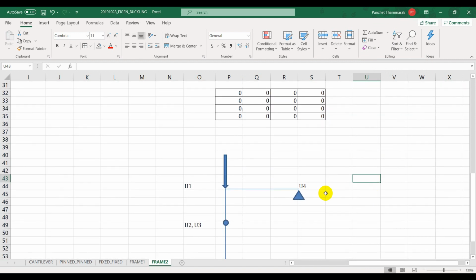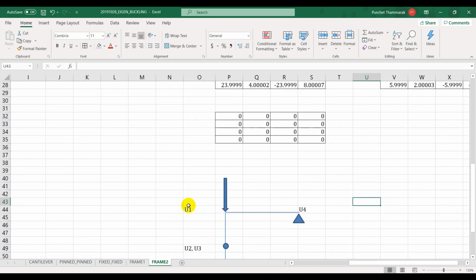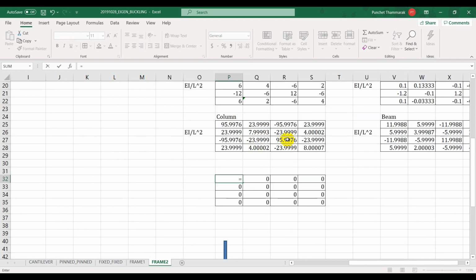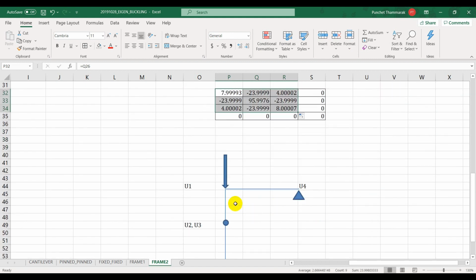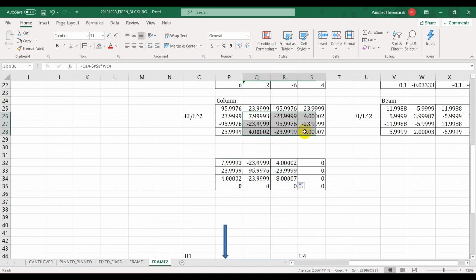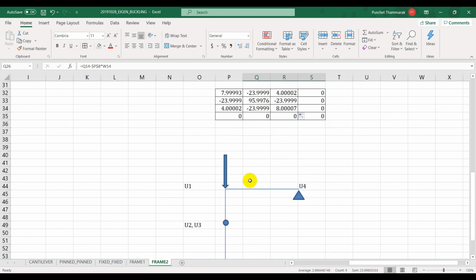Okay. So we take U1 rotation and displacement. So this is equal to this point here, right? This is a contribution from the top column. You don't have displacement U1, the first displacement of this top column, but you have the second displacement at the ending node and rotation. So we take this part here and put them down there.